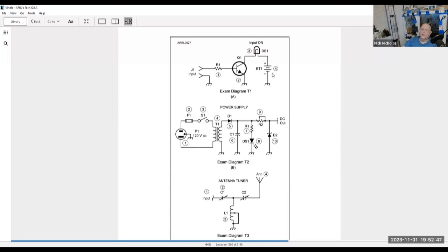In general, a battery has multiple cells, and so we depict that so we know what we're talking about. The reason is that generally a battery cell is only about 1.5 volts, so we have to put them in series in order to get more voltage. Inside the battery package, an individual battery, there are multiple cells, unless they're 1.5 volt batteries.